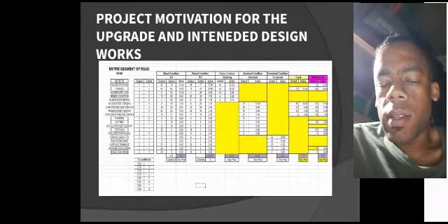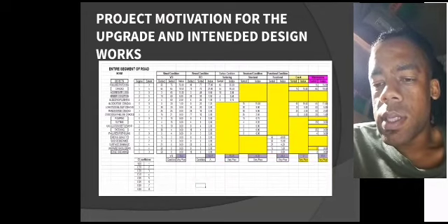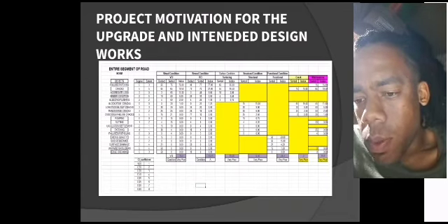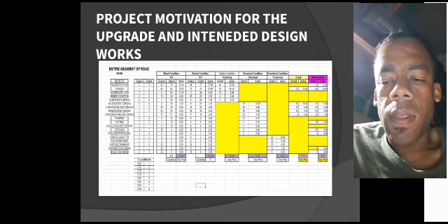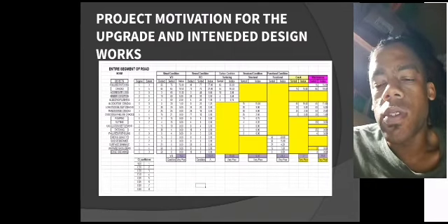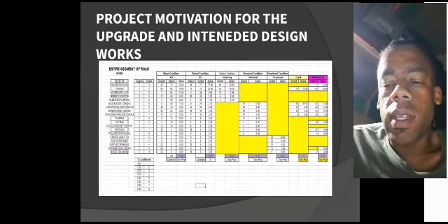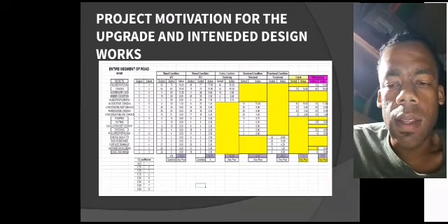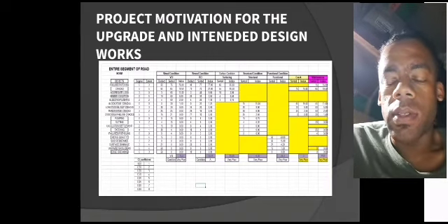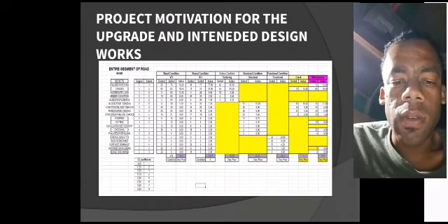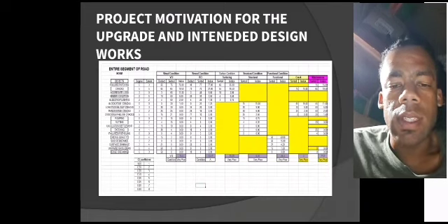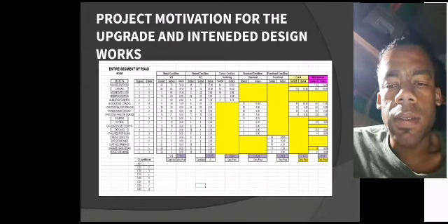The reason for upgrading the road is this table with the information with regards to the visual inspection of the road. As you can see at the bottom, the color that was generated because of the results put in by the degree and extent is purple, and purple is the color that the transportation department uses in order to classify a road as very poor, meaning the road is not in a good condition, it's unsafe to drive and needs to be upgraded.